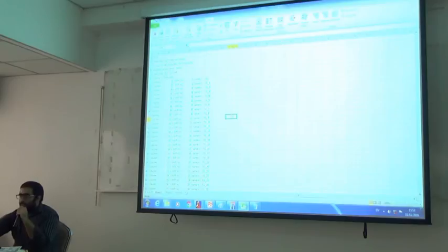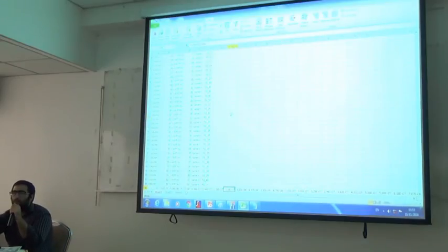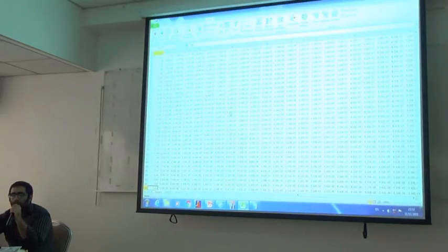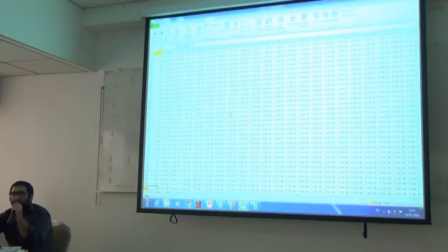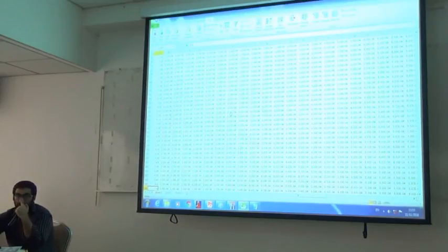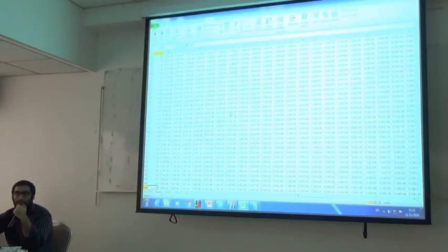So what I will do now is move down from the point where the data starts. You can see that the first column over here is the time step column, and then the next columns are for all of the drifts that are defined over here. Now if I move down from over there, you can see that there is a lot of data that we will get if we are to extract the history results.